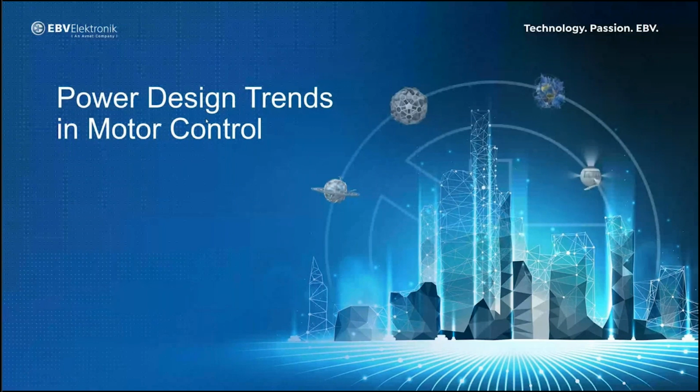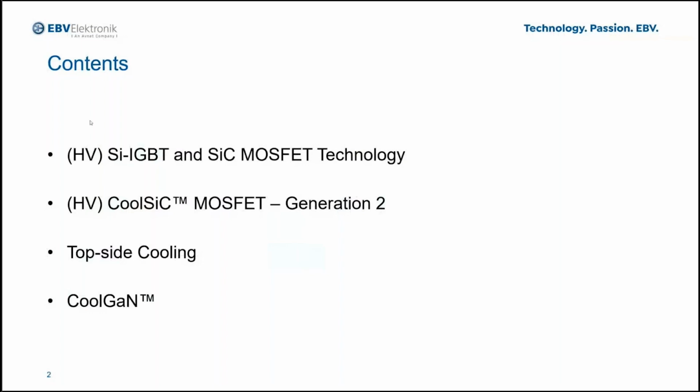Thank you very much for the introduction. I'm going to go through a little bit what are the power design trends in motor control, highlighting the latest technology from Infineon concerning semiconductors which are suitable for driving motors. I will go firstly through what is the state-of-the-art silicon IGBT technology and the silicon carbide MOSFET technology from Infineon. And I will focus concerning the silicon carbide MOSFETs on the CoolSiC generation 2.